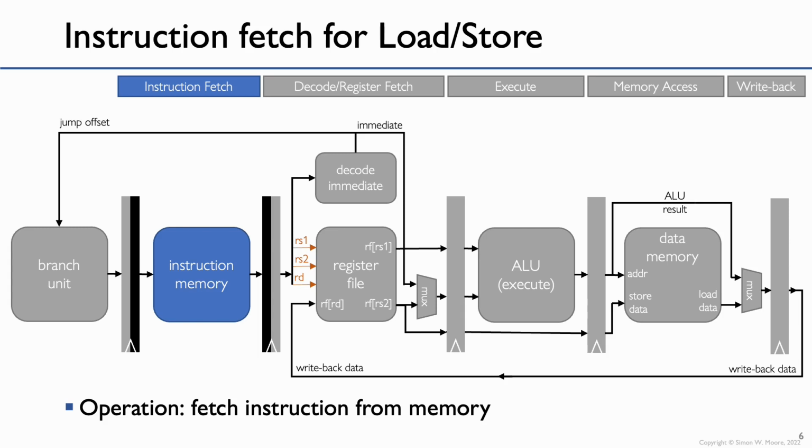And here you'll notice that I've indicated on the D flip-flops that I've split them in half, if you like. So the half that we're using for this step is where the address is being provided by the leftmost D flip-flop, and then the result will go into the next D flip-flop on the next rising edge of the clock.